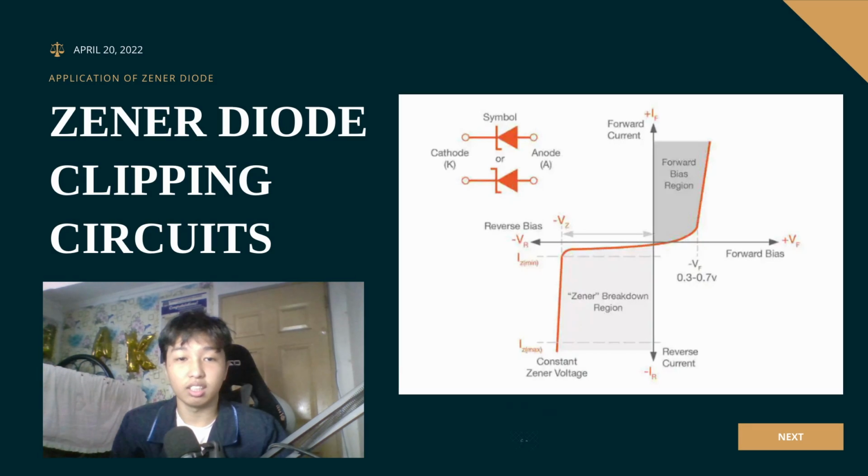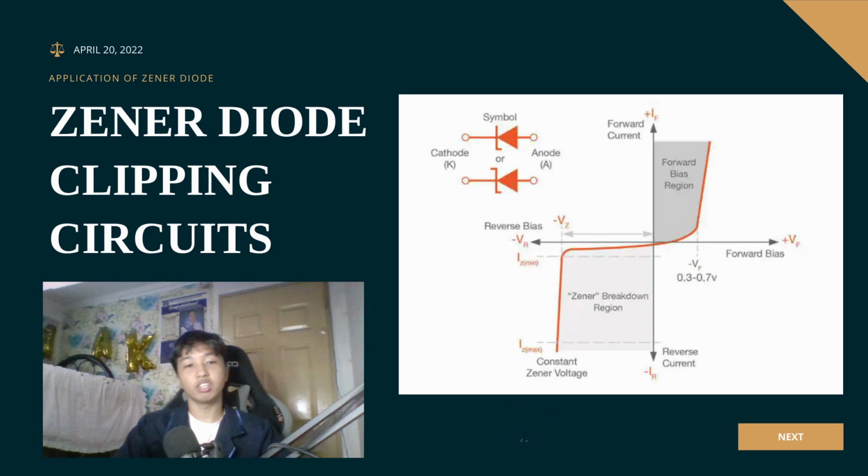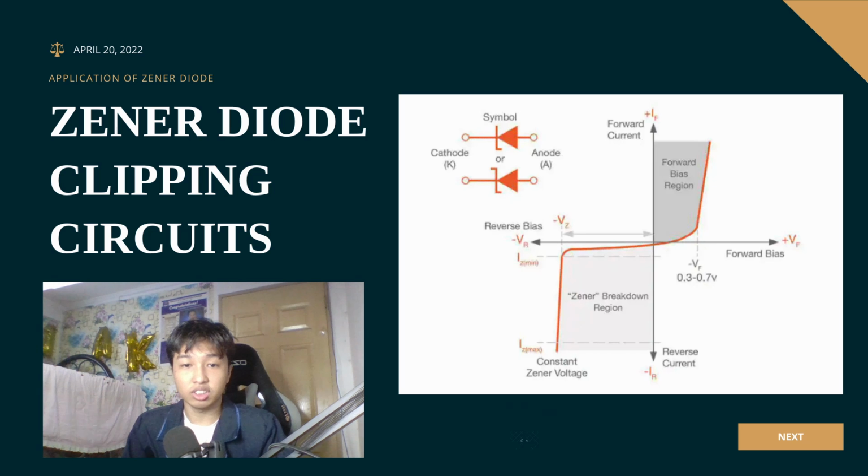A clipping circuit, sometimes known as a clipper, is a device that clips the input voltage so that it does not exceed a predetermined value. This device cuts off the positive or negative peak value of a cycle. An ideal diode and a resistor are the two most fundamental components needed for a clipping circuit. A DC battery must also be supplied in order to adjust the clipping level to the required quantity. The diode functions as a closed switch when forward biased and as an open switch when reverse biased. By altering the battery's voltage and switching the clips, different levels of clipping can be generated.